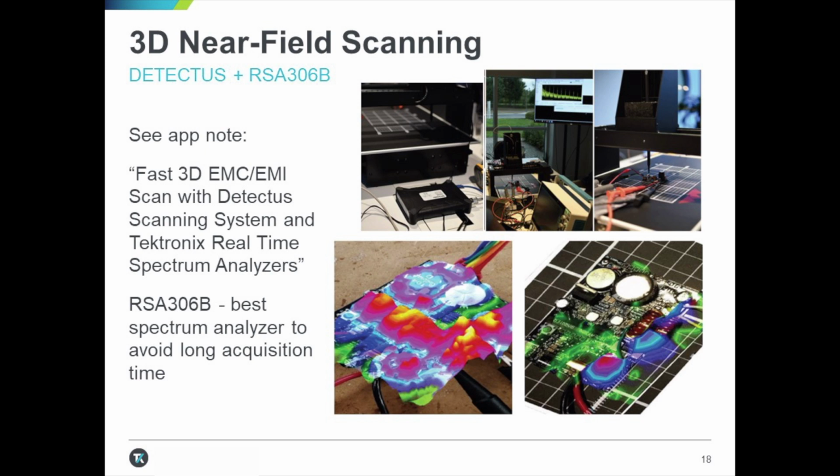They found a solution combining the Tektronix EMC 3D scanner with the Tektronix RSA306B real-time spectrum analyzer, and they needed to run repetitive measurements by scanning with a spatial resolution of 1 millimeter. Running these tests on a relatively large board is time-consuming, depending on the span and resolution frequency used. Prior to using the RSA306B, every single test risked lasting too long with a common spectrum analyzer.